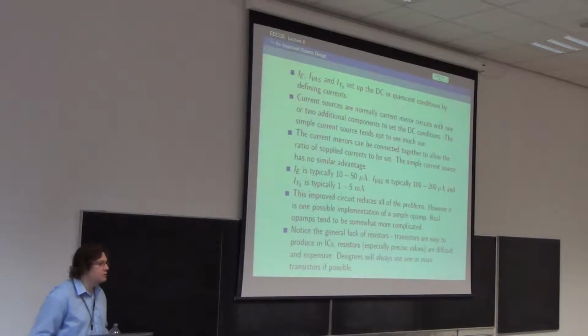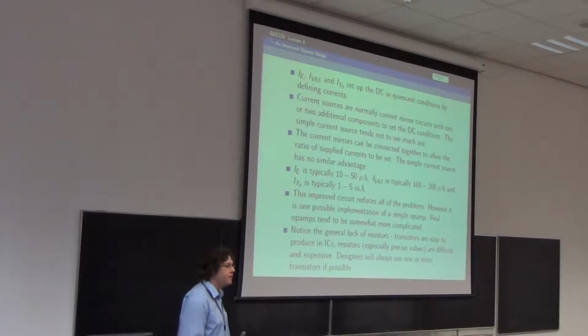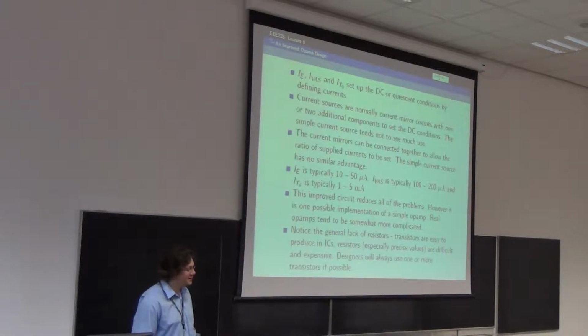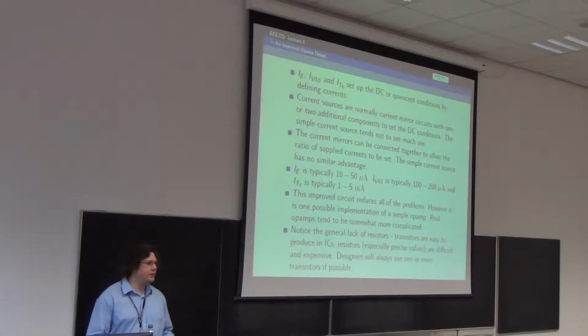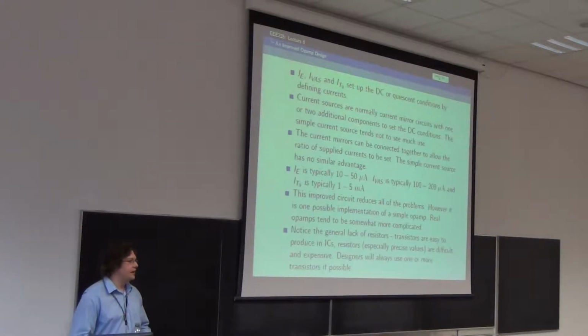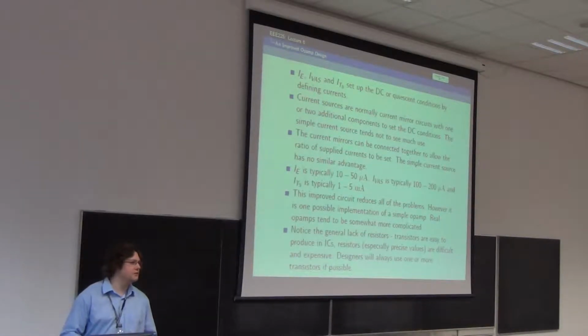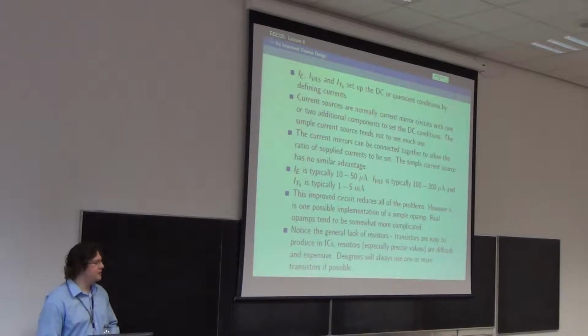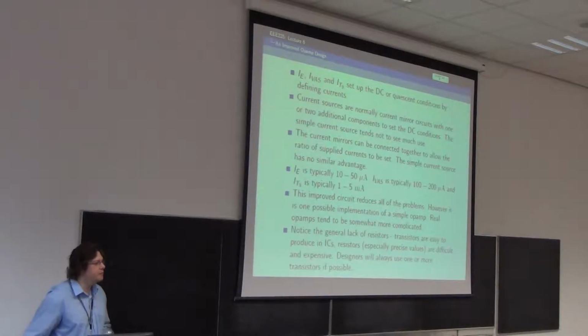The designers will always want to use a transistor if they can, because transistors are cheap and they're probably going to make them anyway. If you want to put a resistor even, in your op-amp, you have to put in a couple of extra processing steps, and generally speaking, if you want a particular value, you have to trim it with a laser, and that takes quite a long time, and it costs more money. Those aren't things you want in mass production. It has to take the shortest time and cost the minimum per unit that you can manage.